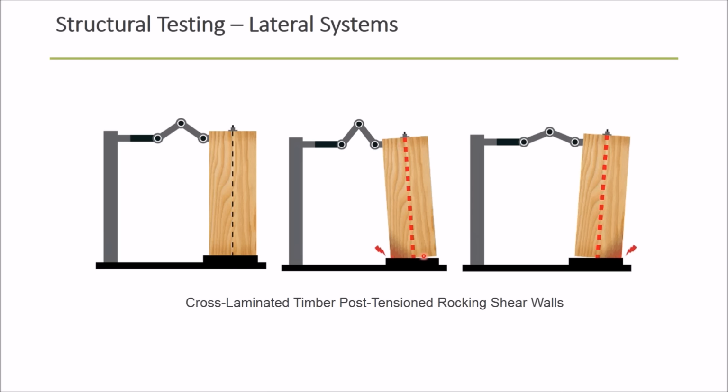In the rocking wall system, there's some sort of shear key to take the shear forces out across the bottom, but there aren't the traditional hold downs at the ends. Instead of those hold downs, which are relatively stiff, this post-tension rod down the middle is a thin enough steel rod that it can flex elastically under the earthquake load, and because it stays elastic, it pulls the wall back together and back to straight up and down after the shaking occurs.